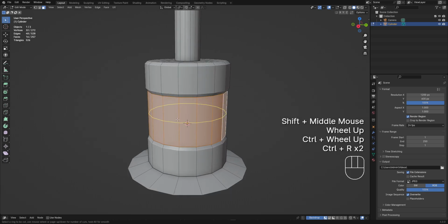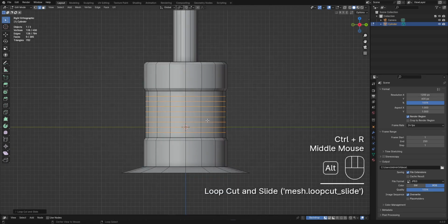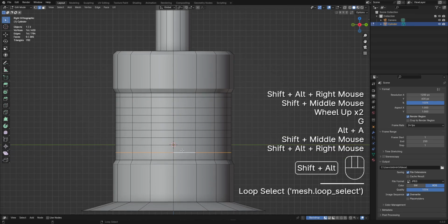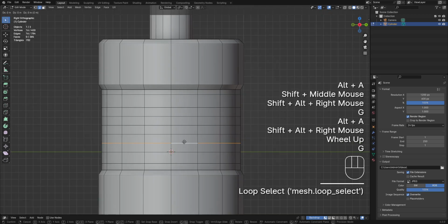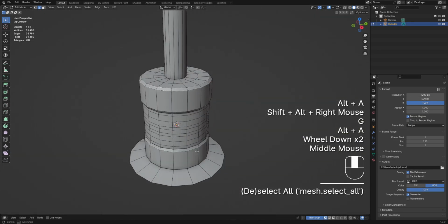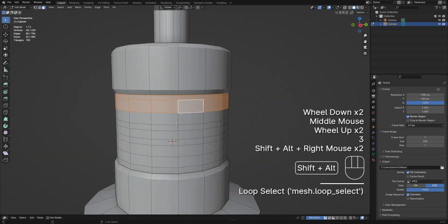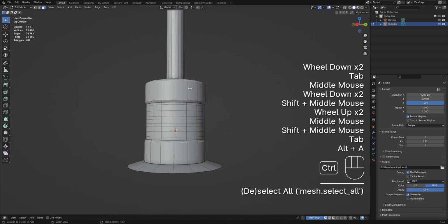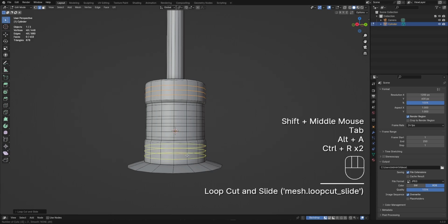So, for example, Control R to create edge loops and press 8. I'm going to arrange the spacing to give the randomizer some different results instead of just dealing with evenly spaced faces. Okay, let's select the faces here. And we're not going to use symmetry. This is asymmetric. And let's include this as well.